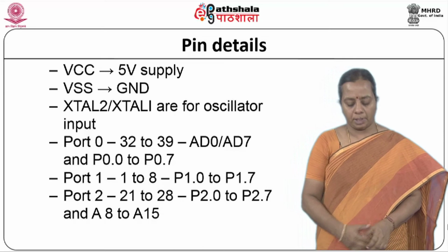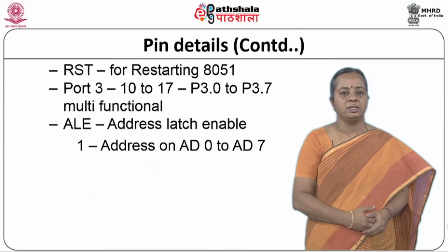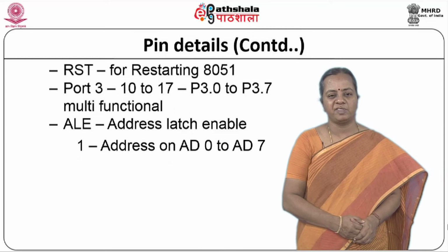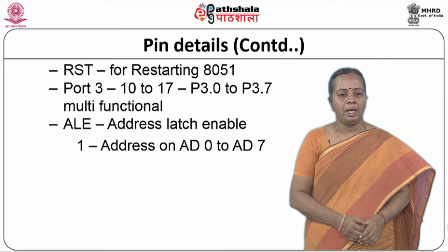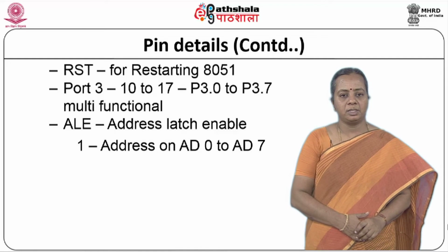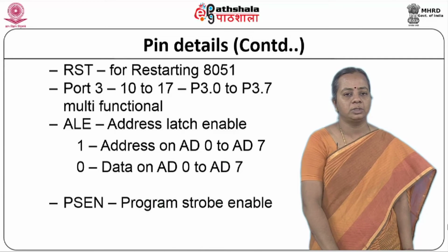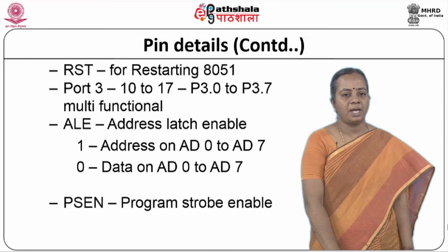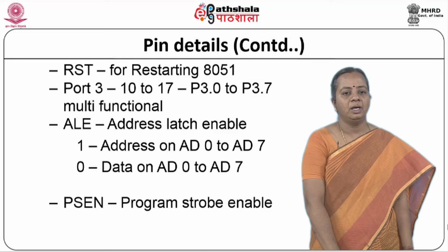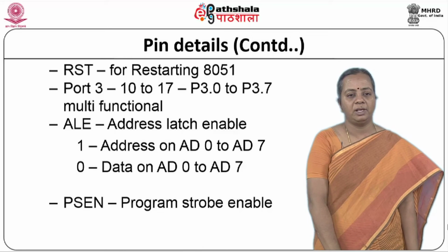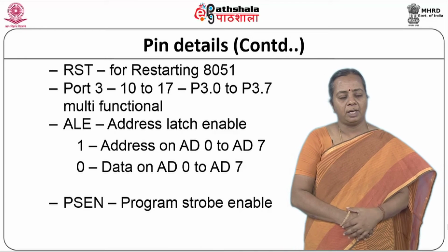Port 2 is also used for sending addresses to memory. The RST pin is for restarting your 8051. If something happens, we can restart the 8051, and for that they have given that particular pin. We also have port 3, which is available from pin number 10 to 17. This port 3 is a very special port where each pin has multiple functions. We will see that in detail in the next slides. Maybe the other things we will cover now.